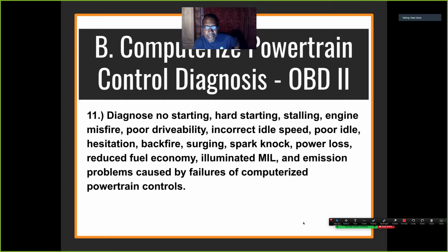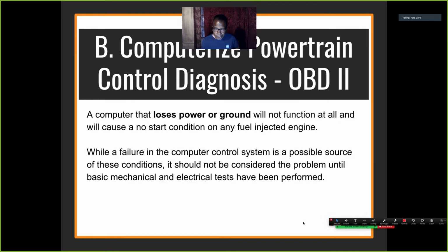Diagnosing no start, hard starting, stalling, engine misfire or poor drivability, incorrect idle speed, poor idle, hesitation, backfire, surging, spark knock, power loss, reduced fuel economy, illuminated MIL, and emission problems caused by failures of computerized powertrain controls. A computer that loses power or ground will not function at all and will cause a no-start condition of any fuel-injected engine.